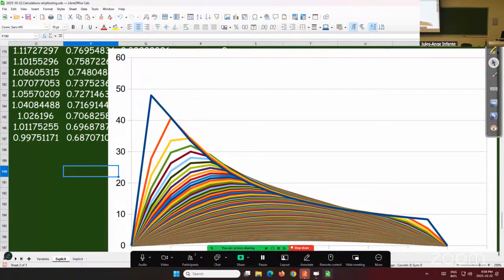If all you're doing is increasing the load, you're not changing the groundwater table, increasing load increases pore pressure much more near the surface than at deeper locations. In deeper locations, over time, you will get an increase.